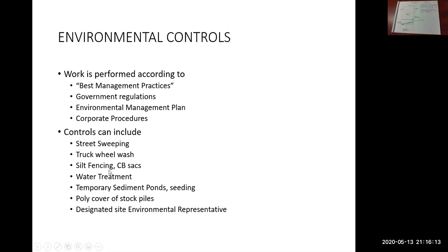Other things like silt fence and catch basin sacks, we looked at those on a previous PowerPoint presentation, as well as water treatment. So you're treating water that's leaving the site. Is it silty? Does the silt need to be treated in some fashion? You cannot allow silt-laden water to leave your job site.